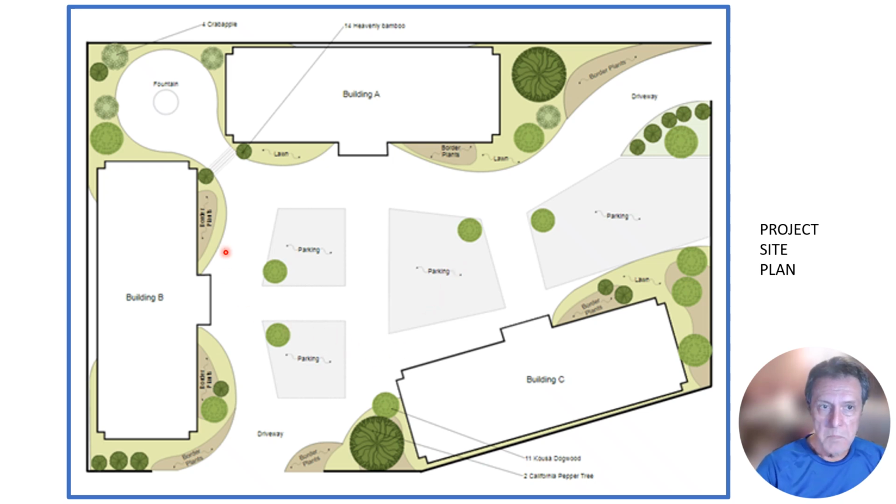Pavement may be on elevations that are close to natural ground, so maybe you don't have to go quite as deep in these areas and sample quite as deep with your exploration equipment. And of course, pavements don't require deep foundations or anything like that. They're generally built on top of a compacted, tight soil or rock subgrade. So as you can see, different areas of the project are going to be treated differently in your proposal, are going to be investigated differently during your investigation, maybe by different types of equipment.